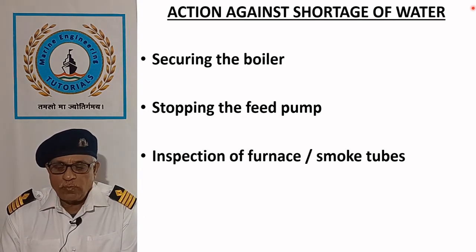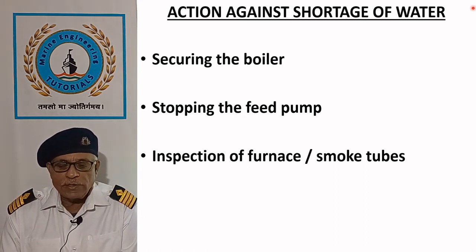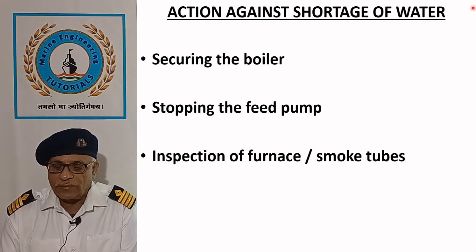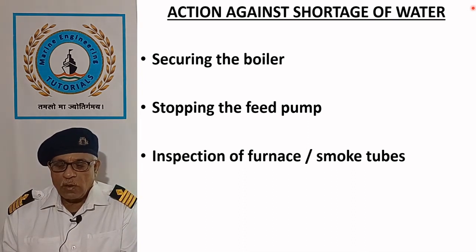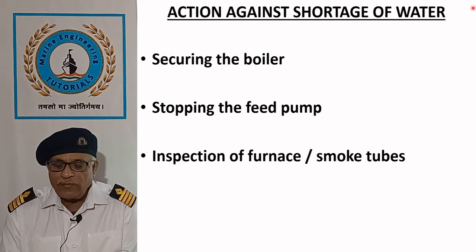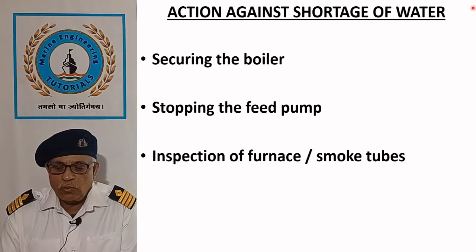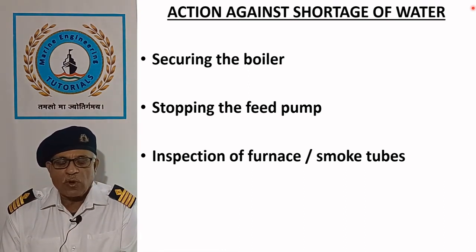Leakage of smoke tube boiler can be easily identified by water leakage from the tube ends. It may require to raise the water level or even pressurizing the steam water side. For identification of a leaky tube in water tube boiler, entry in the furnace is necessary and it may not be easy due to large number of tubes.